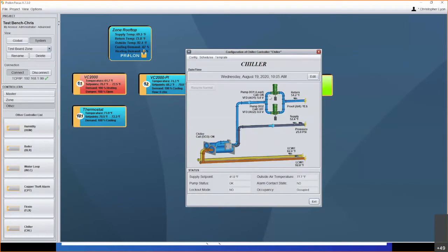Okay, we can see our pumps running. This, of course, is not operating actual equipment. I didn't have a spare chiller laying around to put this on. So I've just put some switches and jumpers and a few resistors in to get these values to read on here. But we can see that pump 1 is our lead. It is trying to maintain 25 PSI, which it seems to be doing pretty well. There is our VFD output at 5.6 volts, and that's holding steady.